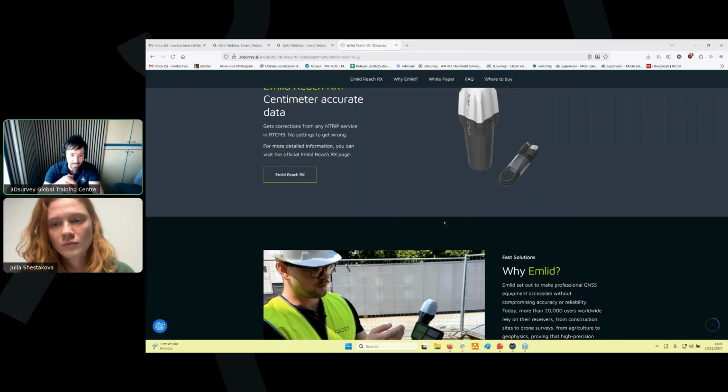Then Yurai has another question. Hi, I have a problem with testing 4.0 right now. I have an error message and CUDA errors, advanced reconstruction. What do you think? I'm not sure if you're testing the videogrammetry or standard photogrammetry example, but it looks like it's connected with the graphic card driver. Maybe just upgrade the graphic card drivers. This is the first step.